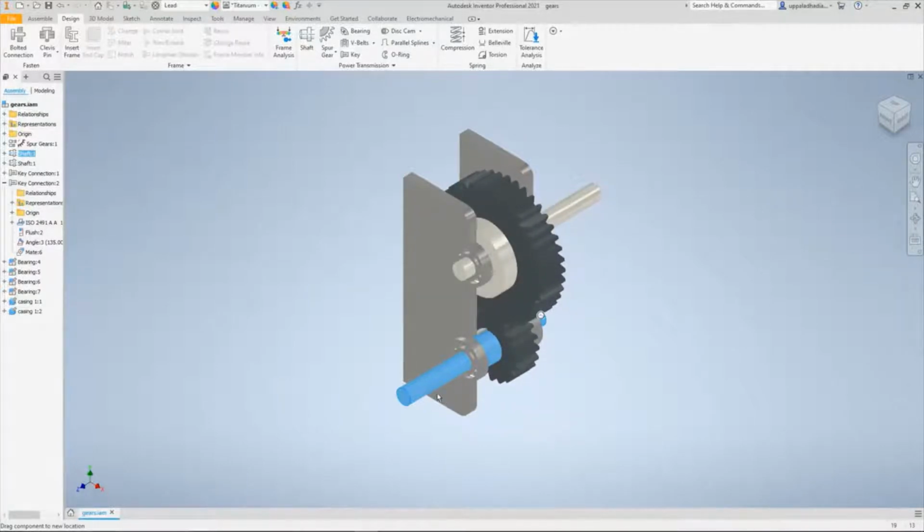We can see there are two shafts only provided. If the first shaft rotates in this direction, then we can see this shaft will rotate in the opposite direction. If an odd number of shafts are provided, then we can see the first shaft and the third shaft will rotate in the same direction. We can see how each part helps.